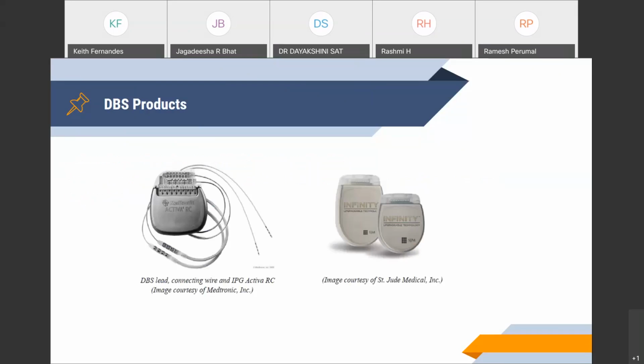So here you're seeing the pulse stimulators used in deep brain stimulation. So you could imagine the size of the stimulator. It should be compact enough to be placed under the skull or under the shoulder. So basically, they are fully implantable devices, meaning that they are going to be placed inside the body. So it demands lower power consumption and smaller size. These two criteria are going to make a huge impact in the selection of the algorithm to automate this procedure.